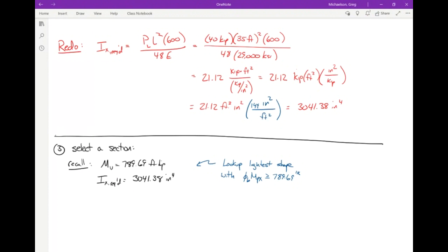Well, the shape though. You're right, it's the 840, but what's the shape? The W24 by 84 is exactly right. Here's the point. The W18 by 97 is the row that has the shape that's just over 789. But why would you pick a W18 by 97 when you could pick a W24 by 84? The W24 by 84 is lighter.